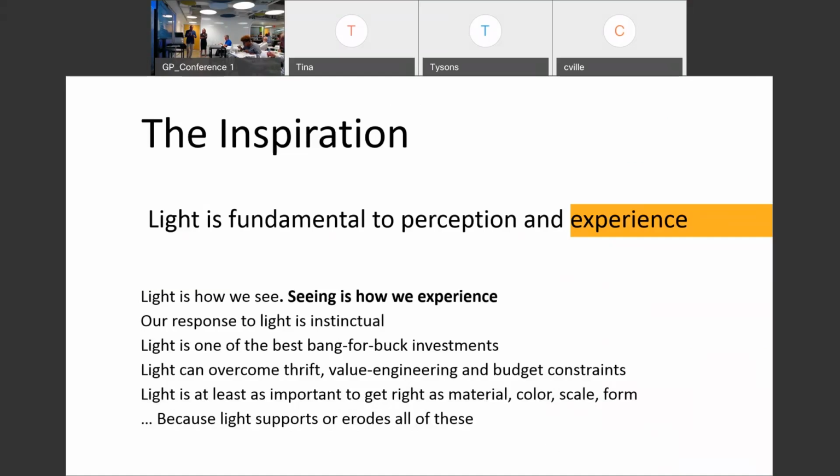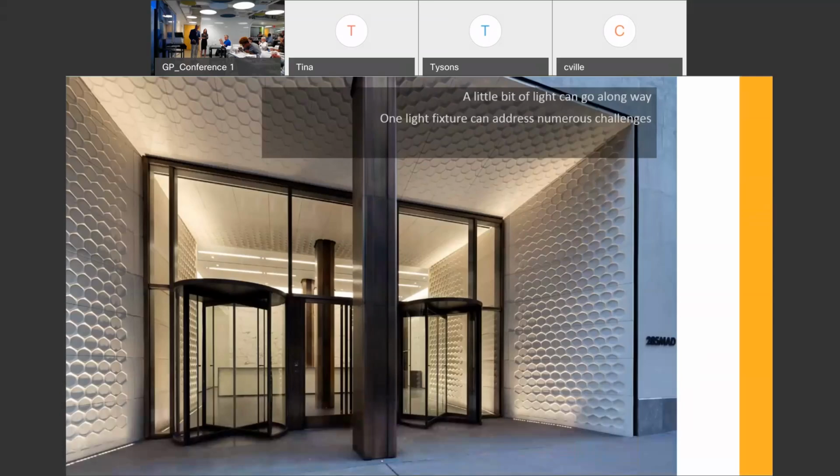So when you come in, it's all about that vertical luminance. So if you're trying to attract somebody in the back, it's not just a flooded conference room like this. If you're trying to get them to the back, let's emphasize more light into the back and light it appropriately where you want it. So when you're making your lighting decisions and understanding the effects you have in mind, you can do more with less.